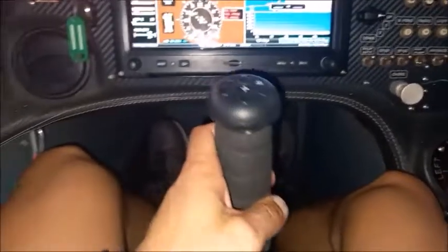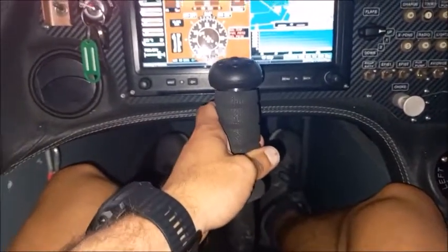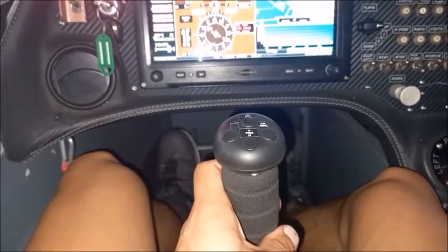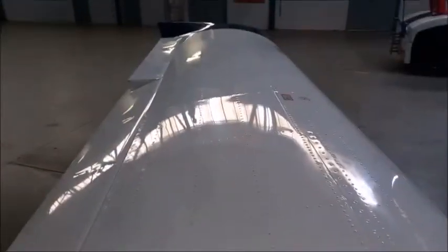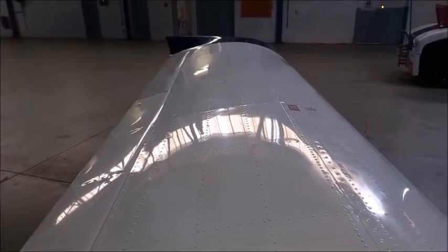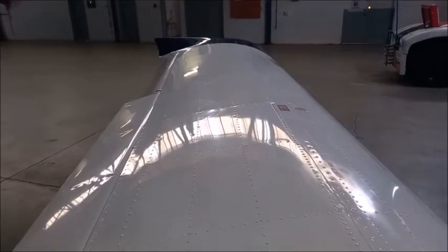This is our control stick, or the yoke. It allows us to pitch up and down, and this is obviously done with the elevator. We're able to move with the ailerons to the left and to the right. As a matter of fact, if you look out over there, you will see the ailerons moving to the left and to the right. So as it moves up and down over there, it actually allows the aircraft to roll to the left and to the right.